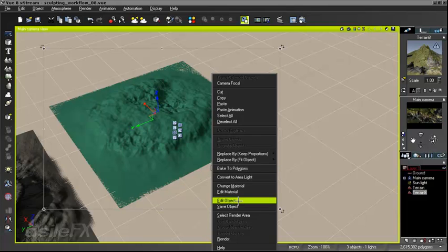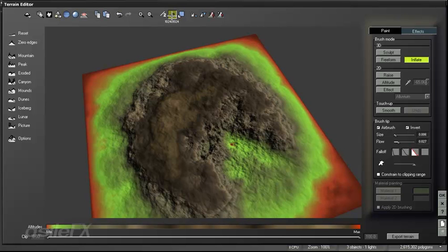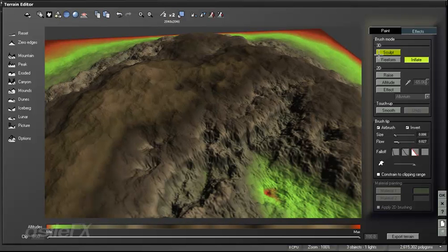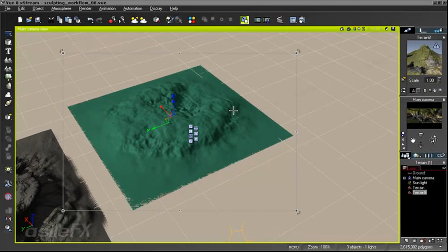What I'm going to do is add in a standard terrain, edit the object, and bring this up to 2048 by 2048 resolution, and now if I choose to sculpt and paint the displacement layer, once you click OK to close the terrain editor, it causes a huge memory leak.